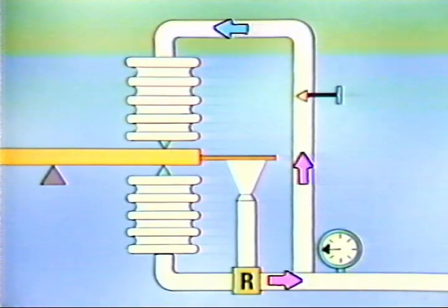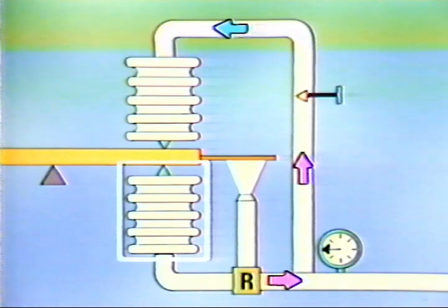On the other hand, if the restriction were closed, the controller would provide less reset action. This is true because the feedback bellows would be able to expand more, just like in the P-only controller illustration, and cause a decrease in output.